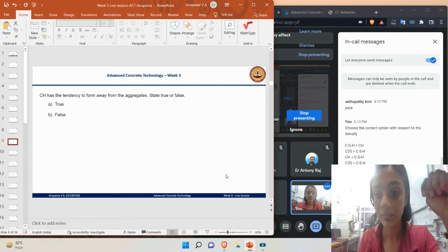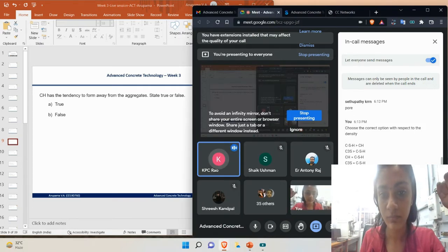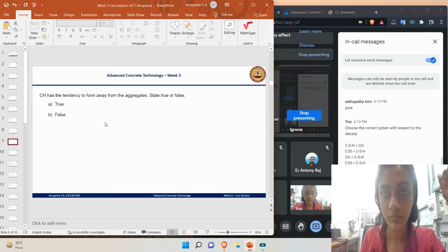Also, we can bring out that in the microstructure, as Sir has explained, the denser particles will be brighter in color, like white. So the unhydrated C3S particles will be white in color, and the CSH, what Sir was trying to bring out, will be grayish all around.